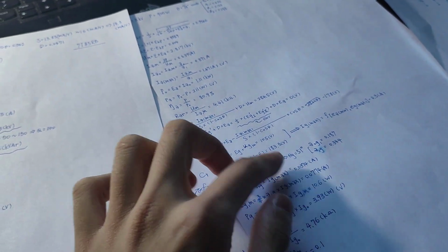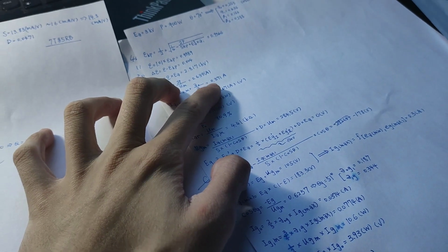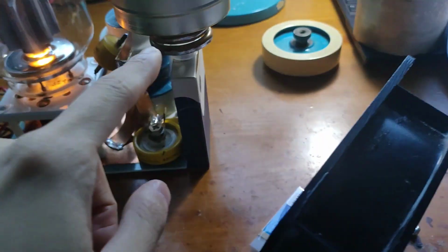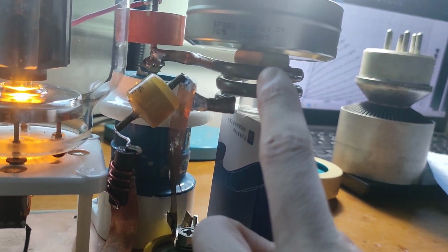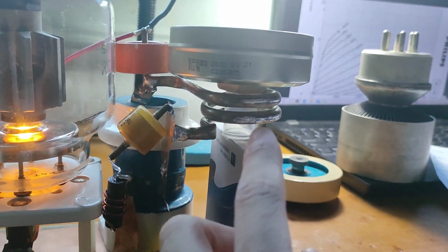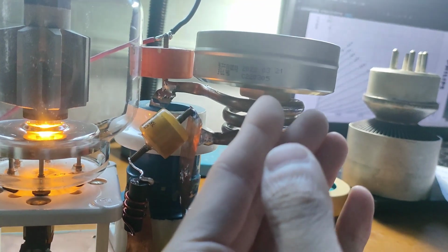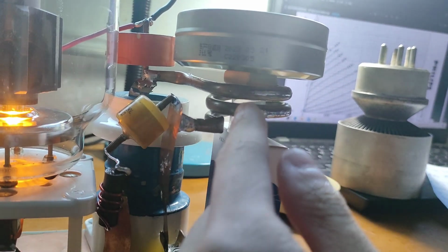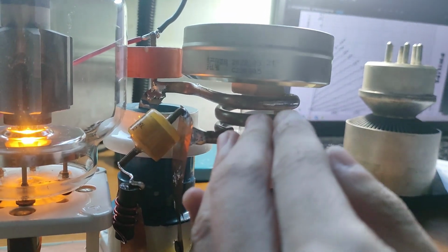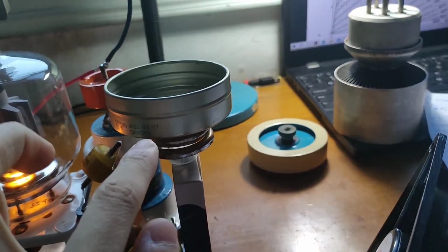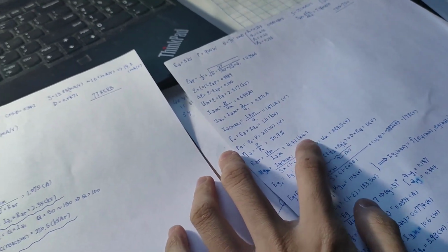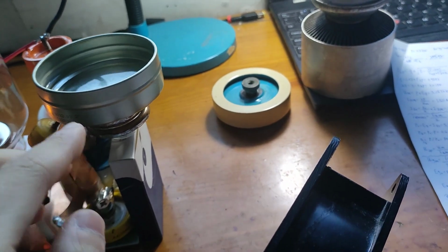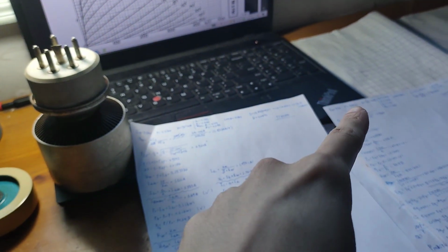That is because we did not take into account the loss of the tank, and also the load here. As you can see, I'm just using a rubber, a cup, and some cards to sustain this one, and the distance between the coil and the plate is not very suitable to get the load impedance to this 4.44 kilo ohms. The load is actually less than that, so the power needed is actually a bit larger than 900 watts. So the cathode current will be higher than we designed.